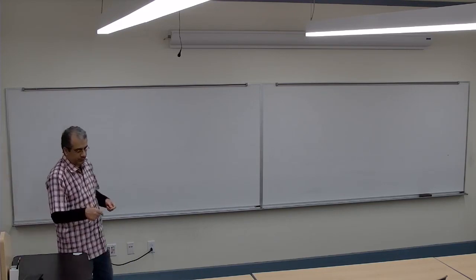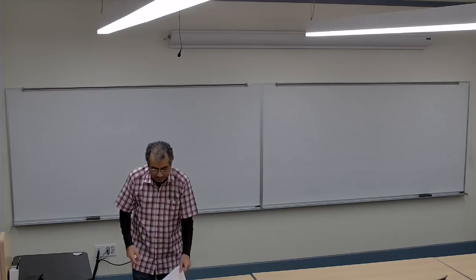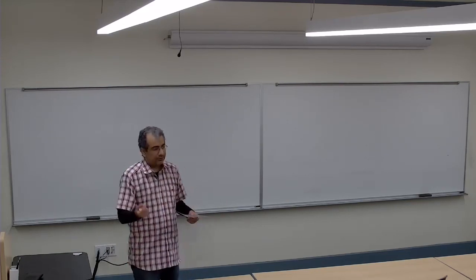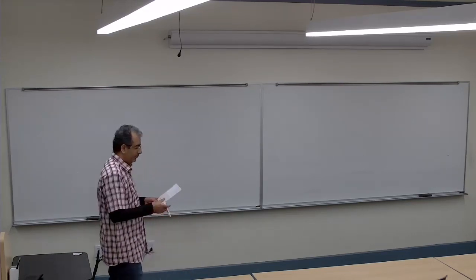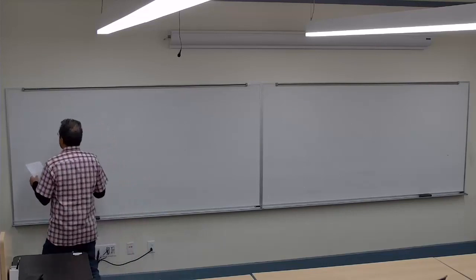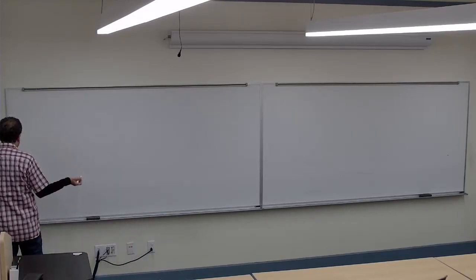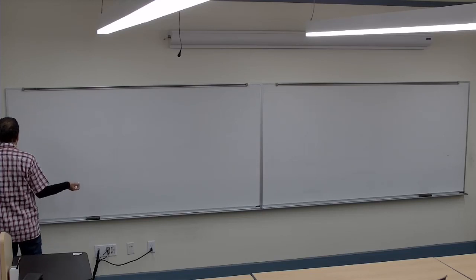So today we are going to start to look at it. If we have more unknowns than equilibrium equations, how can we solve those problems? Up to this point, we couldn't. We just said, okay, we are going to learn how to do it later on. So here's the method of how to do it. Today we are starting to look at statically indeterminate problems.